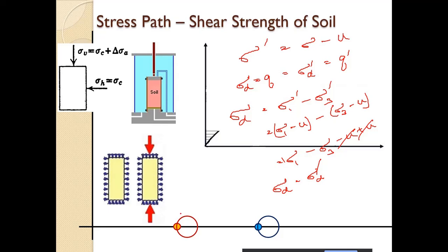All right, so that is one of the critical points that we have to note, because when there is undrained shearing and there is development of pore water pressure, it reduces the effective confinement, but the deviatoric stress remains unaltered or unaffected. So it shears at a very low value of deviatoric stress. So we will see why that is, when you understand how the Mohr circle evolves and how the stress state evolves.